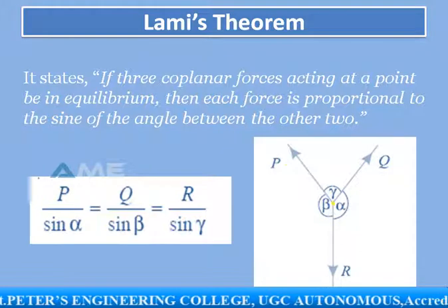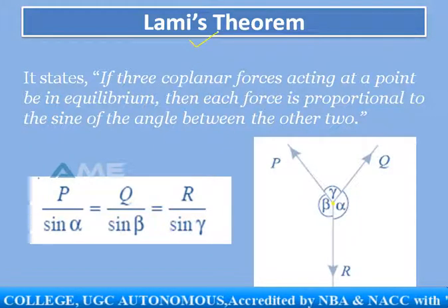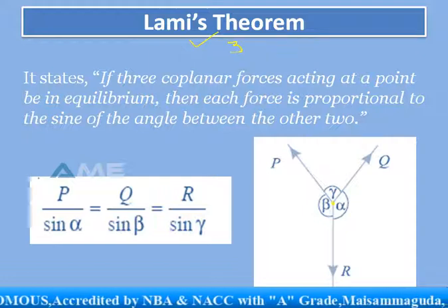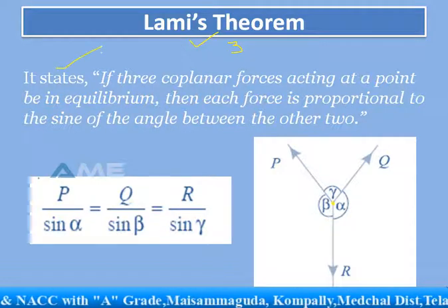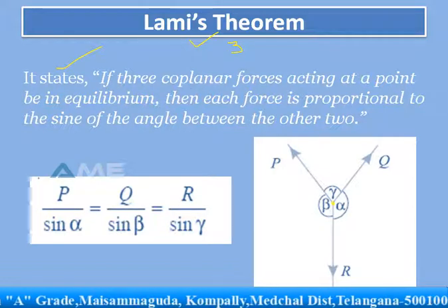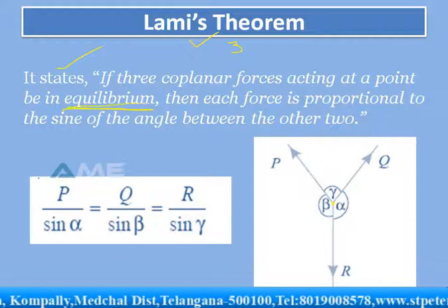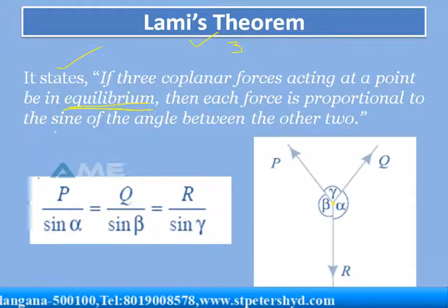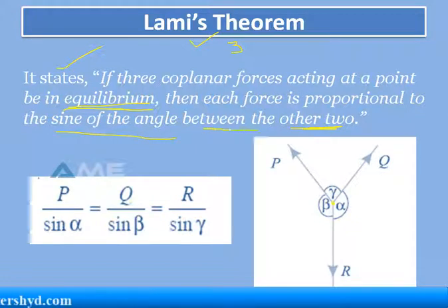Here in Lami's theorem, these are concurrent and coplanar, but we are going to take three forces, and we'll start with the statement of Lami's theorem. If three coplanar forces acting at a point are in equilibrium, then each force is proportional to the sine of the angle between the other two forces. It is the angle between the other two forces that you have to take.